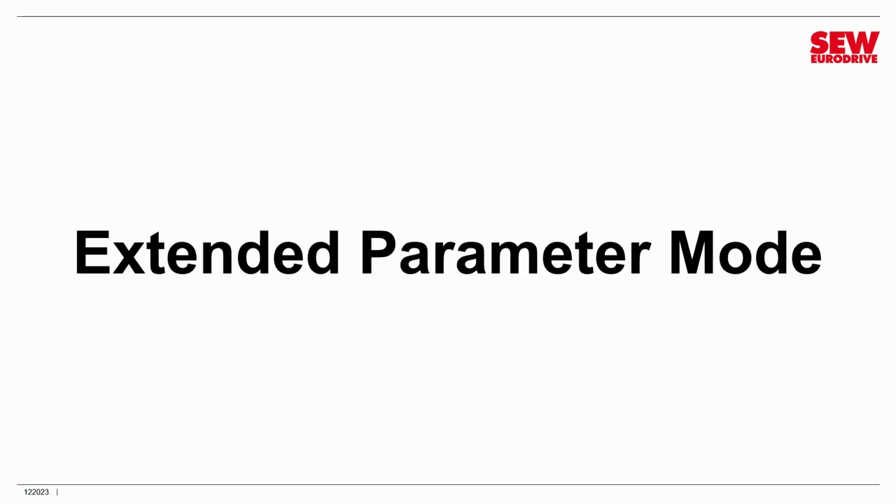All right, well, we're going to pause our discussion of ramps for a few minutes because to go further, we need to access the full parameter tree. As you recall from an earlier session, I mentioned that the complete parameter tree has 283 parameters. We have been dealing with what's called the basic parameters, which is a group of 15 that are necessary to do just a standard quick startup. But to have full control of our VFD, we need to access the entire parameter tree.